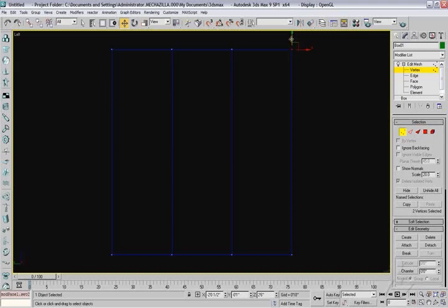The way you do that is you have your transform gizmo here, and you can grab hold of it by the arrow and move it in one direction at a time. If you want to move it down, you could do something like that. Of course, you can move it in two dimensions at a time, and I'll just undo those. And I can grab it by the square handle and move that around also in two dimensions at a time.